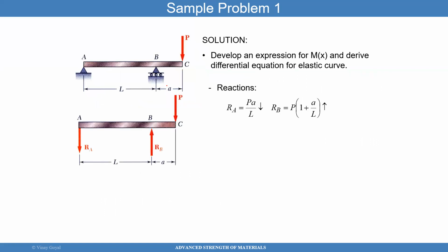Here, what you see is what I've done. I've removed the reaction forces at point A and point B, and I replaced them with a force that's going, you can put it in any direction. If you don't know which way it's going, that's fine. When you do the moment calculation about a particular point, you will see that the sign convention you use doesn't matter. You can make RA going upwards or downwards. It'll correct it for you, because if you take it upwards, it will give you a negative of what I got in this application. But the idea here is you're going to take the supports and replace them by these reaction forces, as you can see in this picture.